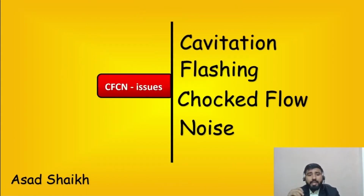Critical application here is CFCN. What I call CFCN is cavitation, flashing, choked flow and noise. For these 4 issues, which are what a control valve mostly faces, the valve selection again becomes important. If you have any of these 4 criteria, then which valve is better for you?